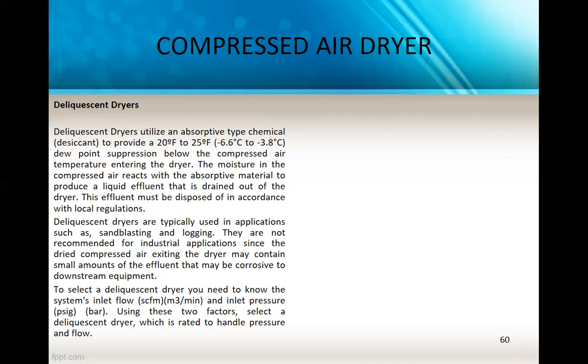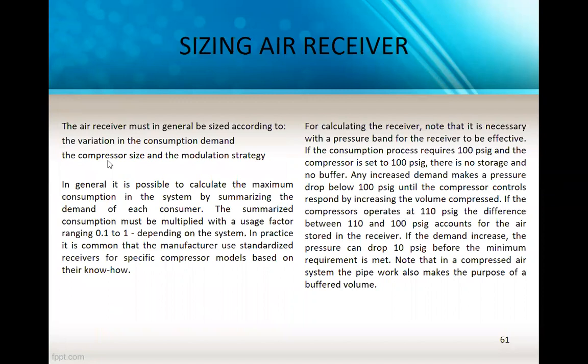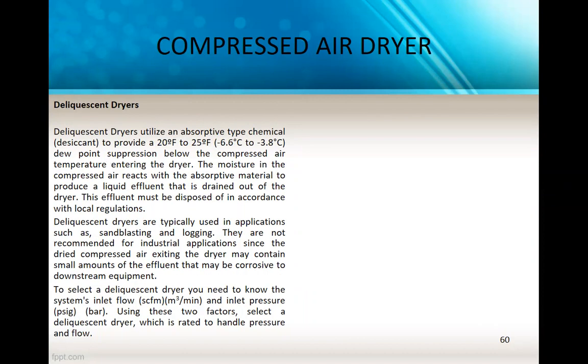Using these two factors, select a desiccant dryer rated to handle the flow and pressure. In the catalog, you will see the pressure and the flow rate, so that is what you select.